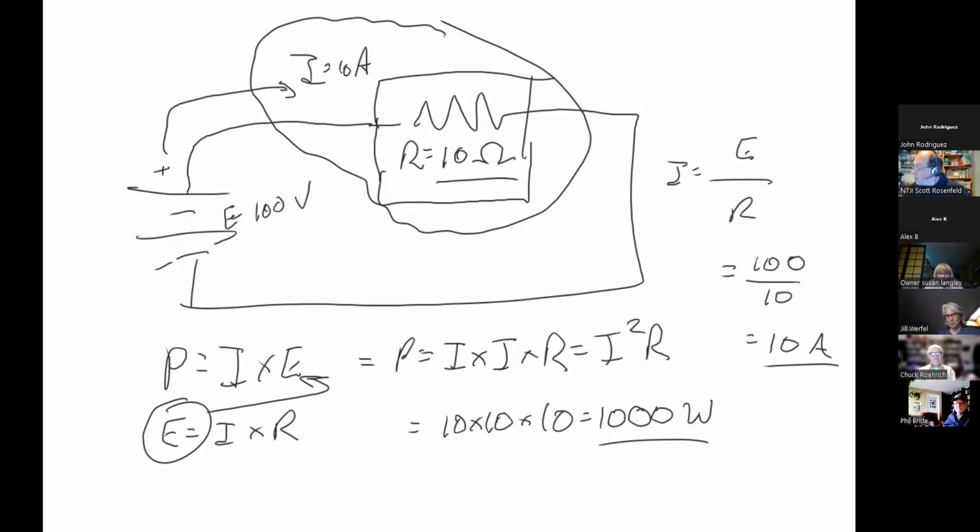What if that resistor is capable of dissipating, let's say, 10 watts? What will happen to the resistor? Uh-oh. You let the smoke out. The first thing that'll happen is that it'll turn slightly red. Let's go through the colors, everybody. It'll turn red, then orange, then yellow, and then it'll probably burst into flames because it's going to be really, really hot. So, not a good idea to do that.